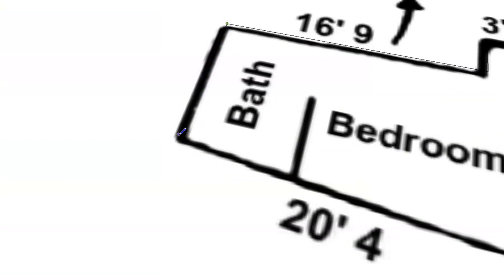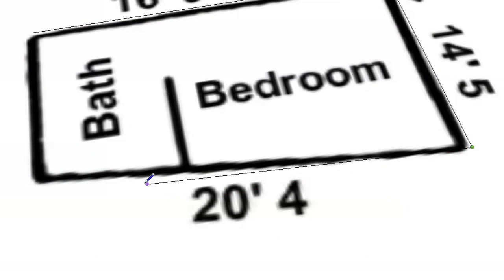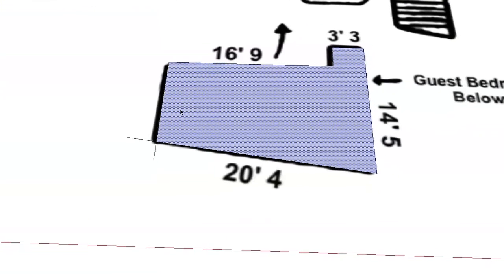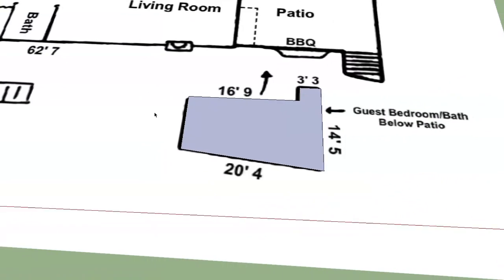Now we don't have a length for this wall here, but we don't need one. So what do we do? Well, I'm going to start over here on this corner and start drawing a line segment, and I'm just going to line it up so that it's roughly the same angle. Line it up as much as I can, and I'm actually going to overshoot so that this line segment is stretching out a little bit more than the actual floor plan is. I'm going to click once there. And now I'm going to take a line from this corner, lock it to the green axis, draw it through and overshoot here. And now you can see when I do that, we have our room here. All we have to do now is just use the eraser tool and get rid of these extra little lines, clean it up, and we've got a perfect shape.